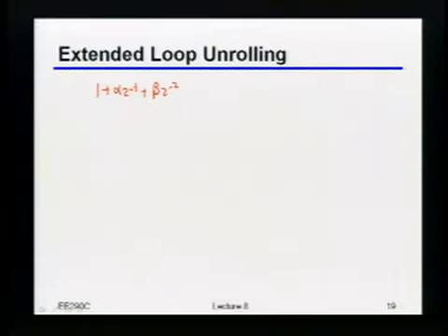Okay, so I think what you're saying will indeed eventually work, but I want to get really specific. I'm a circuits guy, so how many comparators do I need? 4. Yeah, I need 4 comparators, right? Because now I have 4 possible data levels that I'm going to be dealing with. Because now I've got 2 previous bits that could have ISI on me, right? So I have to deal with all of the combinations of those 4 possibilities. Okay? So what would the thresholds of each one of these be shifted by? Let's say this is my V in over here. What would I shift the threshold of each one of those by? And let's just walk through the list.